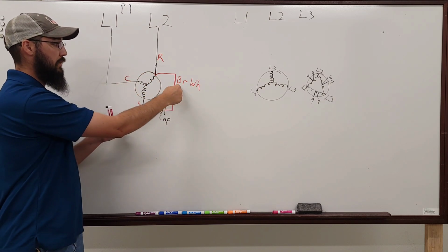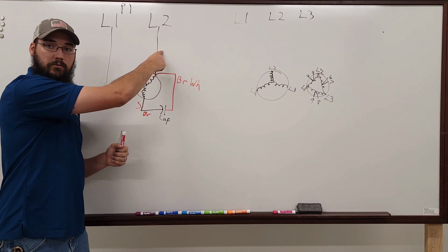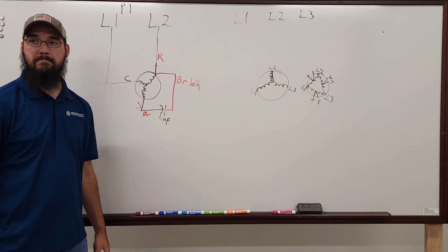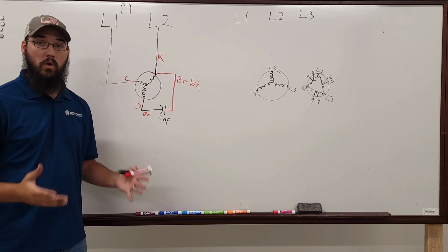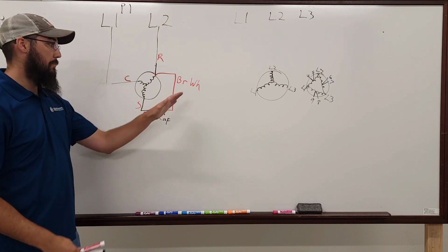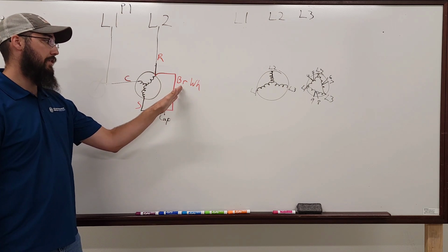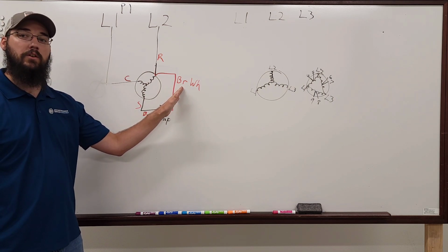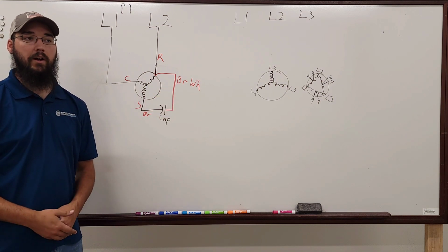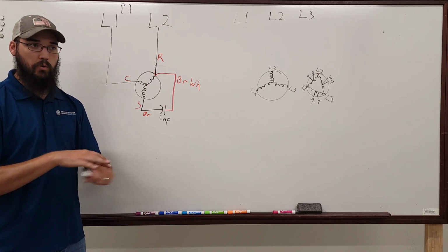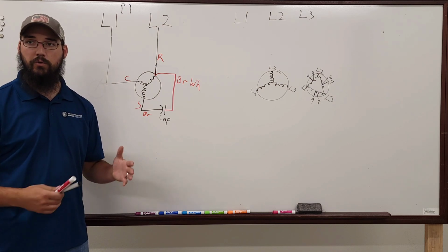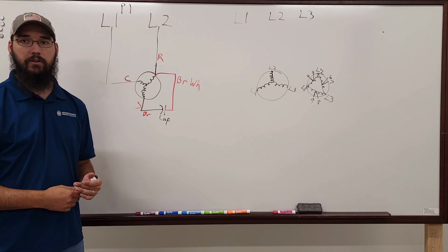It didn't matter if you took this brown white and put it where this violet wire was. You could trade the wires, it would have no impact on how the motor ran. Because at the end of the day, they're the same wire, connected to the same spots on the motor. Correct. And so many times, the manufacturers started doing this because people couldn't wire them correctly. Just flat out, right? They gave you 2 brown wires to plug into, just so you understand without a shadow of a doubt, despite your training or lack thereof, that those 2 brown wires go to your capacitor.